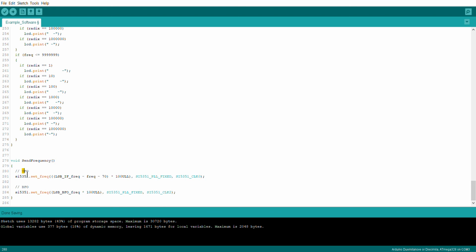So first thing here is the VFO. Remember, that's clock 0. Now you just need to cast your mind back to the drawing we had for the crystal filter. We're doing up conversion, so we need to work out where we are going to place that local oscillator, or the variable frequency oscillator.